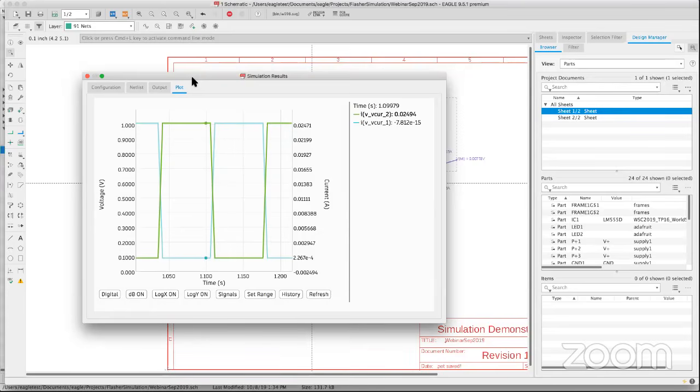Okay, so yeah, usually you want to end at a net. You don't want to start at a net, but it's possible to start at a net. And if the dot did not appear, just go ahead and use the junction command and place your dot there. That's not that big of a deal. Just click on junction and put it there. And when you do, it's going to give you a prompt asking, do you want these two nets to connect? And then you say yes.